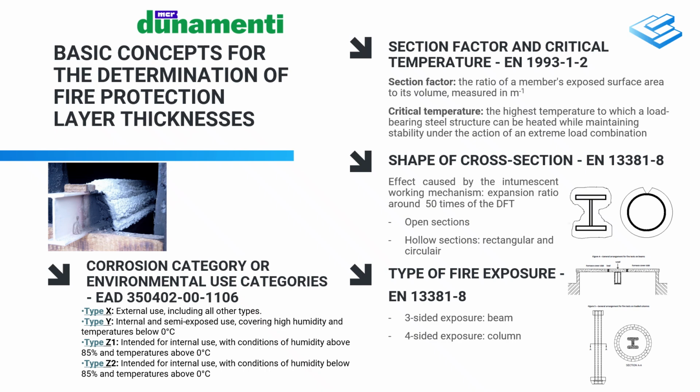The next factor is the cross-sectional shape, which is defined in the testing standard, and at first glance this may not seem like a significant factor. But due to the heat-activated intumescent mechanism of the fire retardant paint, it becomes a key element.